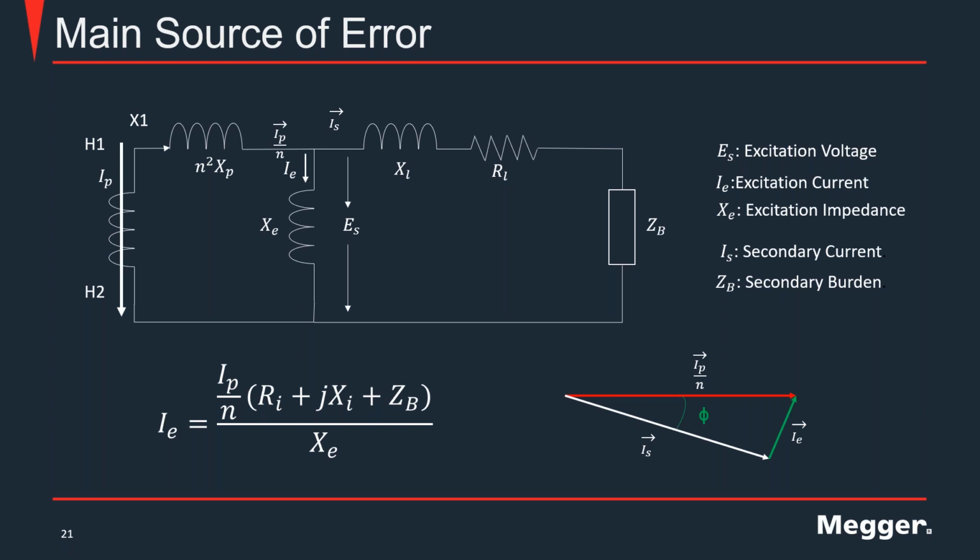Okay. Well, the most important items you have to consider: the first is the primary current that you want to measure. You would choose a CT that gives you a measurement within the rated nominal of the secondary, and that does not exceed that measurement. That would be the first element.